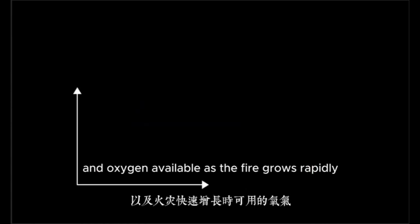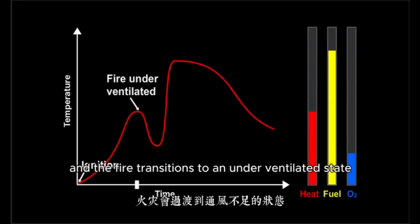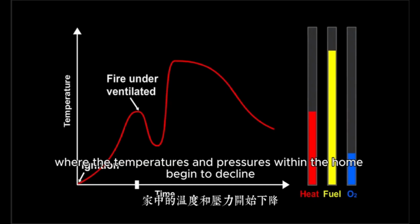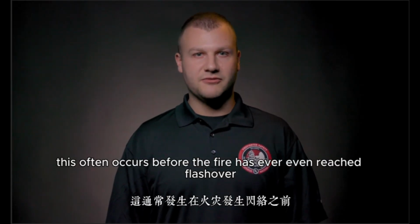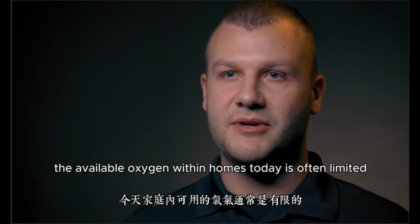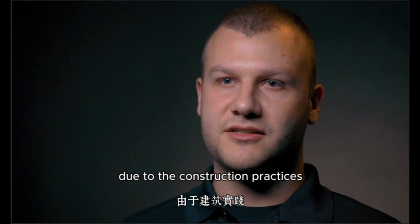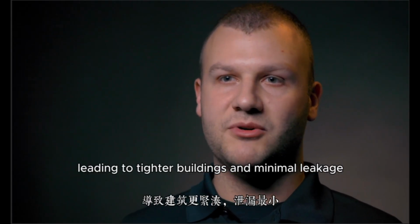As the fire grows rapidly, the available oxygen within the space is consumed and the fire transitions to an underventilated state, where the temperatures and pressures within the home begin to decline. This often occurs before the fire has ever even reached flashover. The available oxygen within homes today is often limited due to the construction practices which focus on energy efficiency, leading to tighter buildings and minimal leakage.